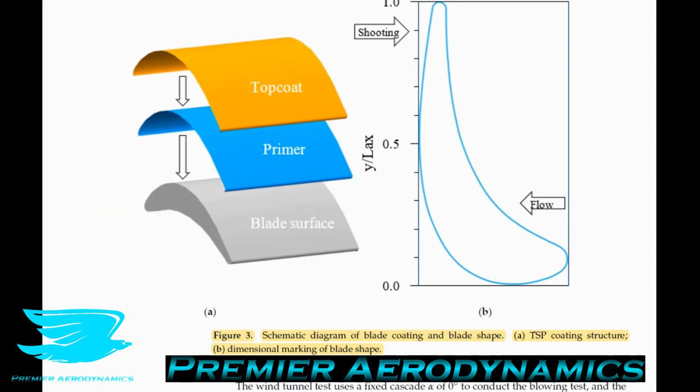So the smoother the surface, usually the better. Well, this is a tricky point, because if you're using a RANS model, the turbulence models you use are based on empirical data, the different coefficients that you use. So they're really just based on average surface roughnesses in the end. So you want to have effectively an average surface roughness, which is kind of like a machine finish, which is usually smoother than a painted surface. So you do want to smooth it to some extent with sandpaper, and that's what they're doing here.